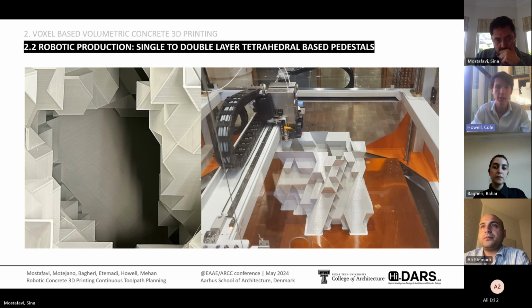The results of the prints helped predicate the design despite the sheer slopes of the pedestal walls. The first print was structurally unstable due to using a single wall layer, but this was solved after doubling the layers, which better emulated the print thickness of the concrete.